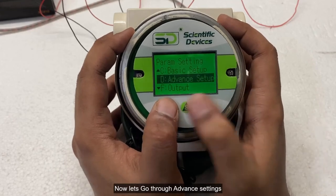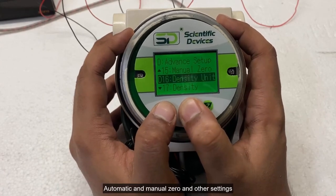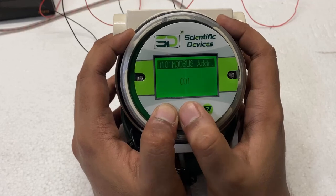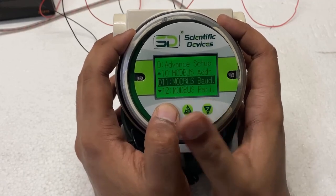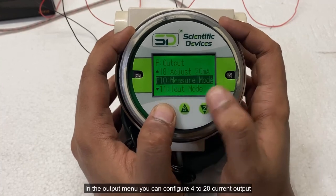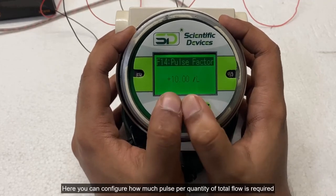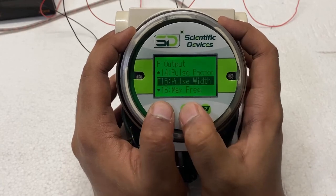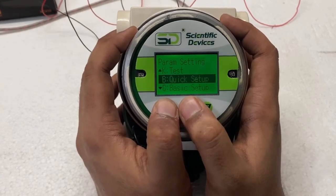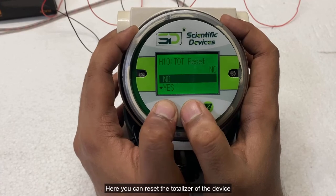Now let's go through advanced settings. Here you can configure Modbus settings such as address, baud rate, parity, automatic and manual 0 and other settings. In the output menu you can configure 4 to 20 current output, pulse and alarm output and other output setting. Here you can configure how much pulse per quantity of total flow is required. In total set menu you can configure totalizer related settings. Here you can reset the totalizer of the device.